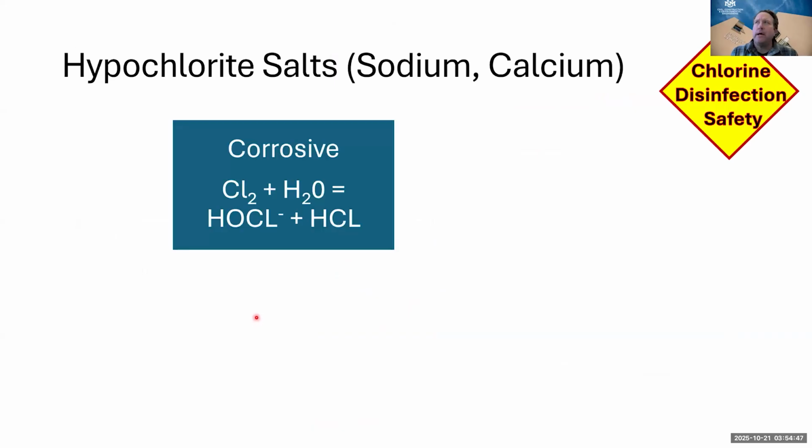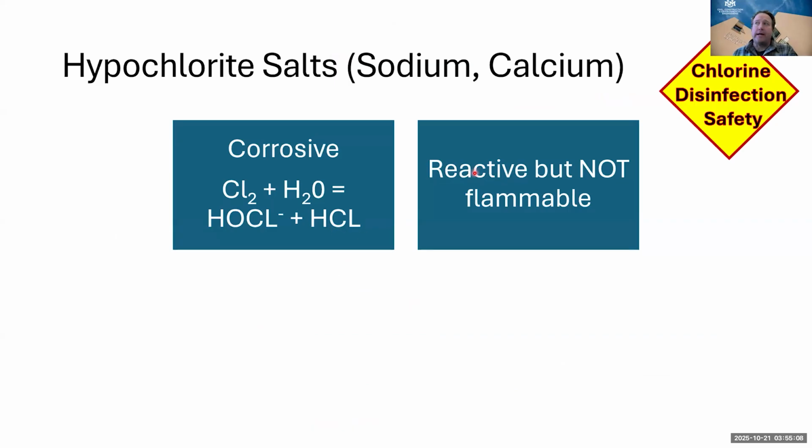All right, so let's talk specifically about sodium and calcium hypochlorite salts and some of those specific chlorine disinfection safety things about these. Again, they are corrosive. They start off as a base and then you add them to water and they can form the hydrochloric acid. They're reactive, so they can react with things, but they aren't flammable.